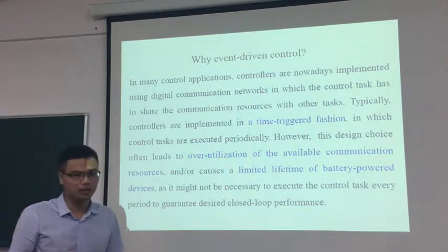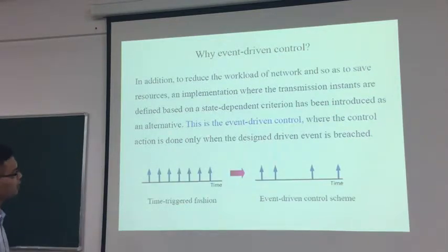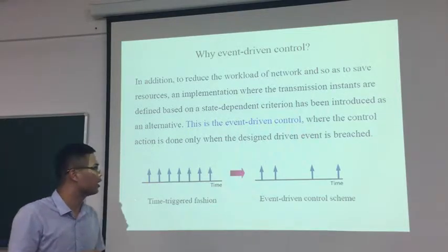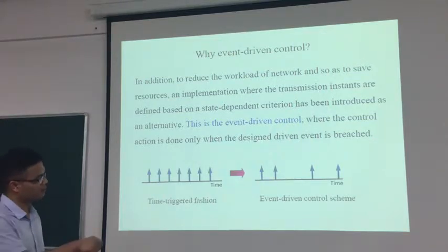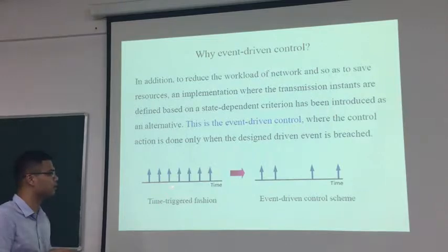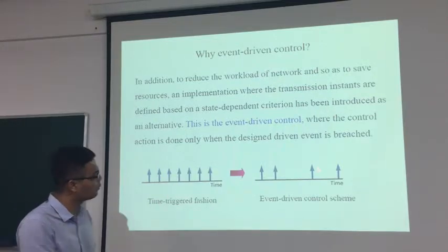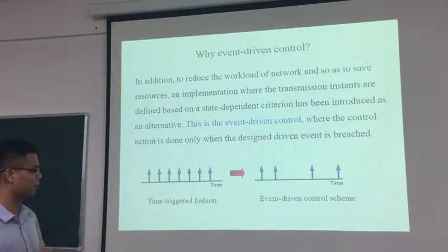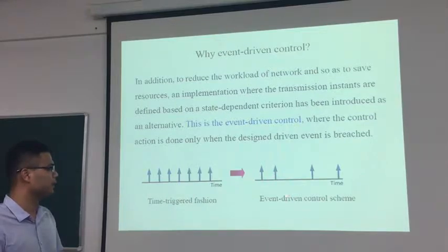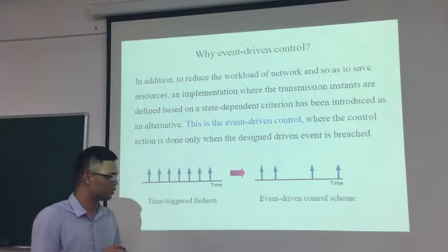To improve this, here we introduce another control style, which is called event-driven control, where the control action is done only when the desired event is breached. For example, we look at this picture. The left one is the time-triggered control style, and the right one is the event-driven control scheme. From this picture, you will see that the number of updates is smaller for the event-driven control scheme.